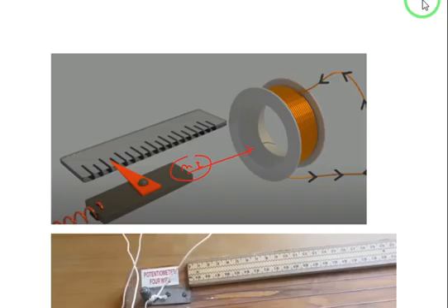Whenever current is flowing in this, what happens? The flux will be produced. This flux gets connected with the moving iron material, therefore it keeps on moving based on the flux produced. Due to this moving iron material, hysteresis loss will occur. With this, frequency changes. Due to frequency changes, the impedance of the coil will change. Due to the impedance change, the reading of the instrument, whatever the needle is showing, will change. Like that, it gets affected.